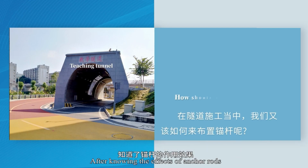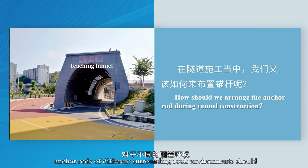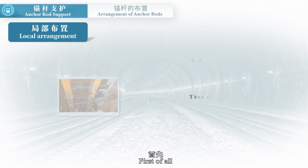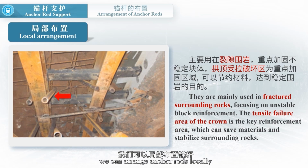After knowing the effects of anchor rods, how should we arrange the anchor rod during tunnel construction? In fact, anchor rods of different surrounding rock environments should be arranged in different manners. First of all, for the fractured surrounding rocks and the tensile failure area of the crown, we can arrange anchor rods locally and focus on reinforcing the unstable area, which can save materials and stabilize surrounding rocks.